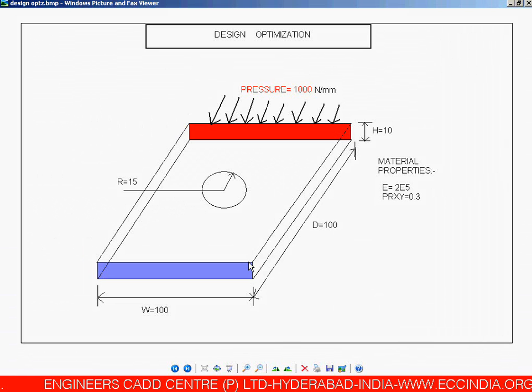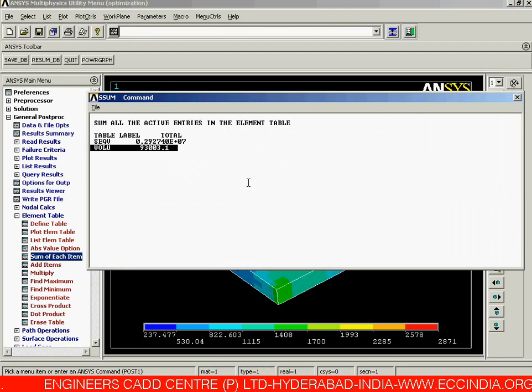For the manual calculation of the volume, we can easily say it goes to 1 lakh. But once we go for the elemental volume, we can see this particular value is reduced over here to 93,003. So in that way we are getting a lesser value. That means it has some percentage of error. We need to improve our mesh. So we need to try to get our best mesh quality to get the best results.